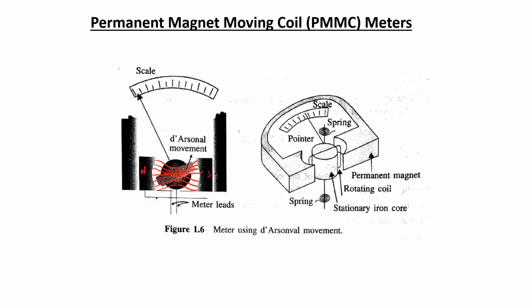The curved pole faces are used to ensure that the moving coil edge is facing the magnetic pole perpendicularly, so that the magnetic field line enters at a right angle into the edge of the coil, so that the torque experienced by the coil is maximum, and it stays uniform throughout the different angles of rotation.